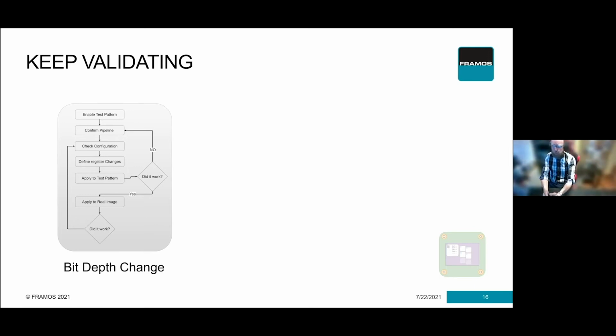So let's say you wanted to do a binning system where you reduce the resolution but increase the sensitivity of a particular sensor, and you also want to have external slave control, for example, and at a custom resolution. The first thing you would do is get that test pattern working, and then you would convert the fundamental parts of it. So in this case, we changed the bit depth because the kit we got with our AVB had a really good 12-bit set, but it didn't have an 8-bit set. By the way, they do, so this is slightly theoretical.